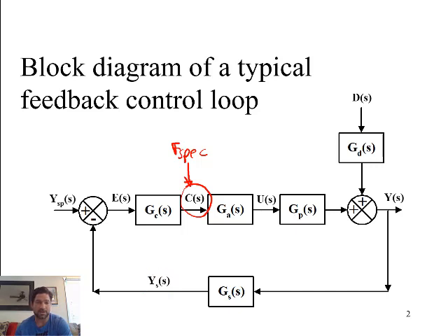What we're doing here is we're now closing the loop. By closing the loop, what that means is that now the sense value from the sensor is going to be compared to a set point. So instead of changing the actuator, now our input is going to be a set point to the control variable. We care about the control variable coming out of the process. We're going to have a set point, and this set point is going to be compared to a sense value, and it's going to give us an error.